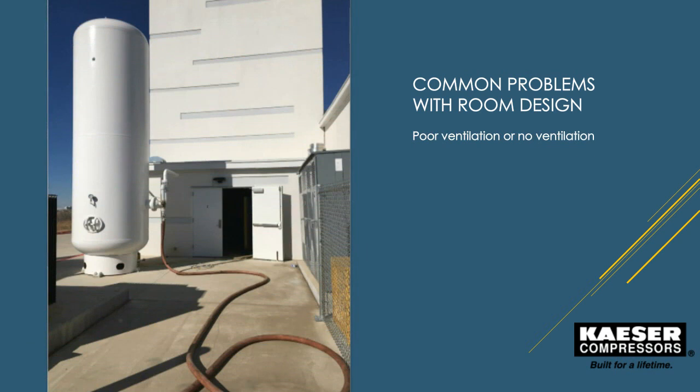One of the other top items is poor ventilation or no ventilation. What we're looking at here is a storage receiver, a big white tank outside the compressor room, and then you see the compressor room to the right with those double doors. What's missing from this is the louvers and the ducting. Louvers would bring clean, fresh air into the compressor room, and the ducting would remove that hot discharge air from the compressor room. We see none of that.